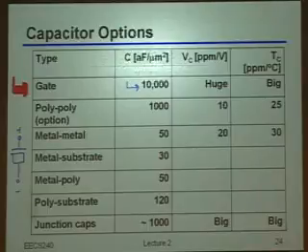Okay, MIM I will talk about in 1 second. There's a version of MIM which is basically metal-metal, but obviously with a thinner insulator. We'll come back to that in 1 second. So I guess DJ was maybe going to answer the question. Why is the gate the really dense capacitor there? Yeah, the oxide is thin, right? We just said a second ago that it was a 1-point-something nanometer oxide. And trust me, that's way, way thinner than any of the other oxides in the entire rest of the chip. Simply because of that, that's typically the highest density capacitance you can get.